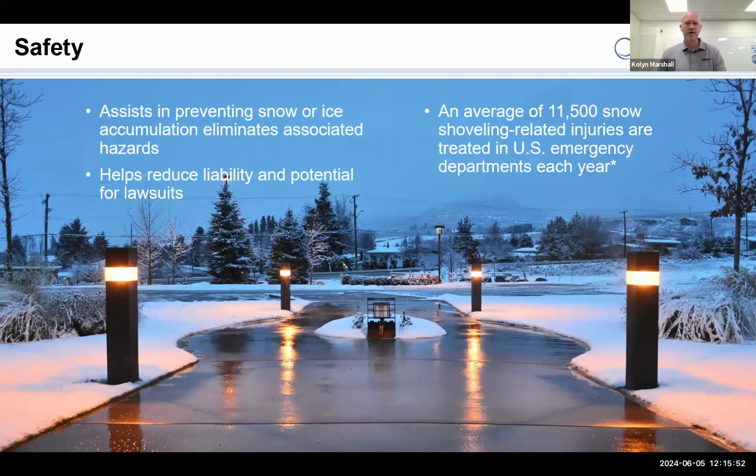And it's real hard to shovel and blade stairs. So a lot of times the stairs are the areas that get the least amount of attention, and they're the ones that have the highest risk of falls. Snowmelt systems are able to be installed. You can typically conform the piping to meet the profile of the stairs. And so you get a nice even melting across the tread and the riser of the steps.